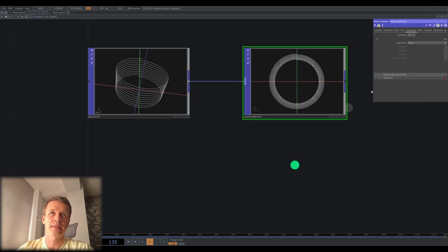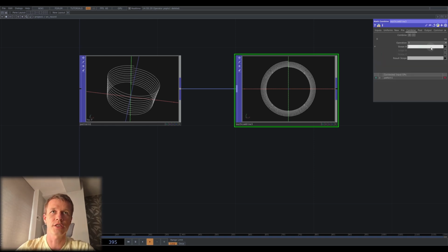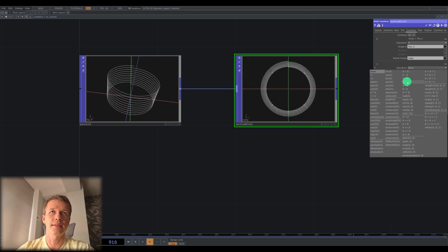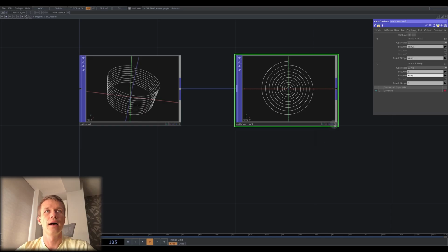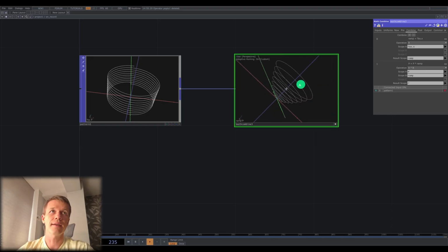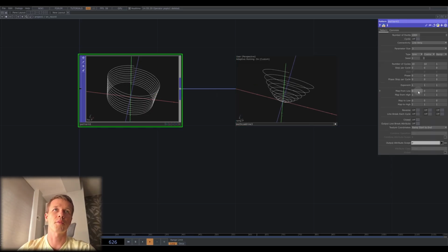I will rename this attribute to make it easier to read, because it's not a texture, it's just a ramp. And now I can use this ramp as a radius multiplier. I take p multiplied by this ramp, and now near the start the value is close to 0 and the circle is very small, and linearly along the line the radius grows. And the spiral is just a simple circular motion with a radius that changes.